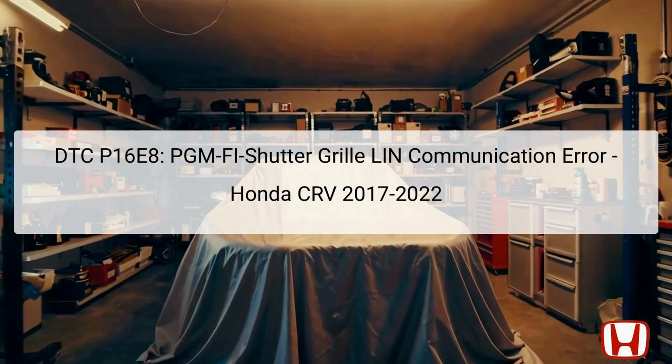The shutter grille operates by controlling airflow to the radiator and engine compartment, thereby maintaining optimal engine temperatures while enhancing fuel efficiency as it opens and closes according to the engine's cooling needs. In this context, the issue may stem from various factors, including communication interruptions between the shutter grille system and the powertrain control module, PCM, which serves as the brain of the engine management system and home to numerous DTC codes that could shed light on the underlying problem. Understanding the components involved and their functions is critical for effective troubleshooting.